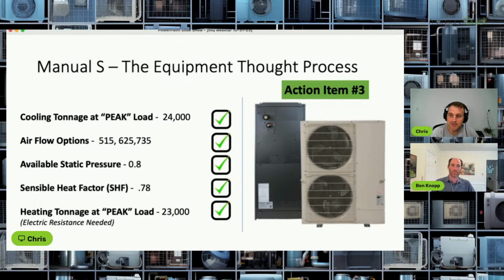But the sensible heat factor of the 2.5 ton was running about, I think, 0.83. So our water removal capacity was not going to be as good with that 2.5 ton. Plus the extra capacity meant our run times are going to be shorter. So it wasn't going to be the best fit for summertime operation, but it was going to be an awesome fit for wintertime operation, right?